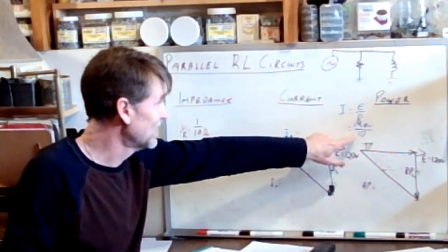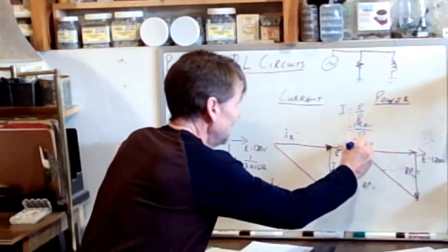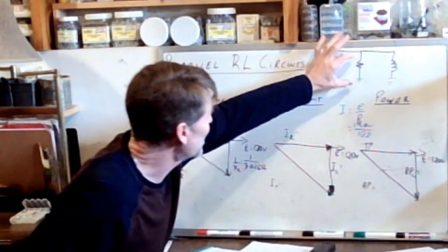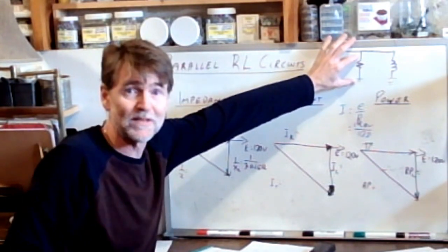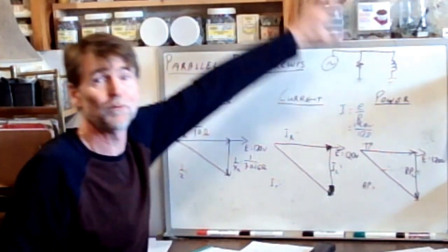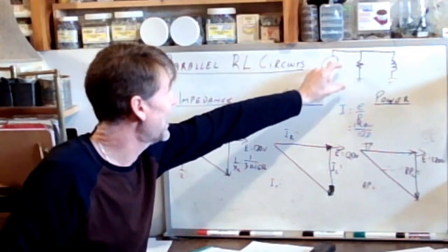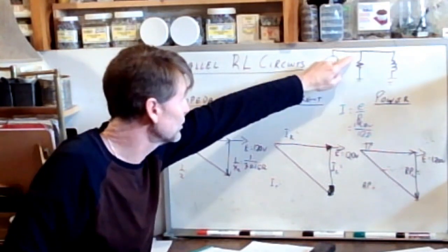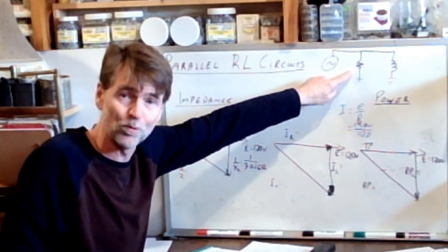Ohm's law means 10 ohms is exactly the resistance in the circuit, okay. We're now just doing math on the numbers in this branch. Okay, the fact that there are other parallel branches doesn't really factor into what we're trying to do and understand right here. There's 120 volts dropped across that 10 ohm resistor.